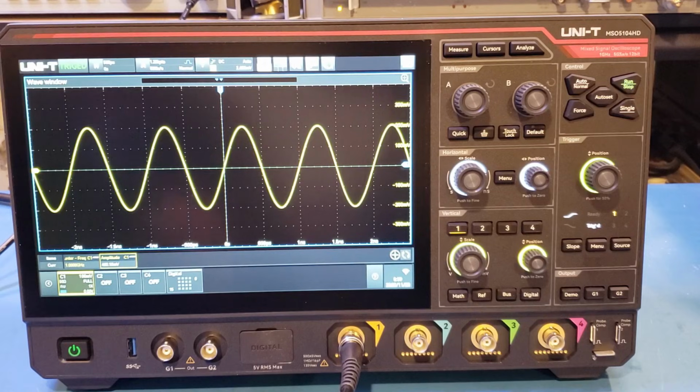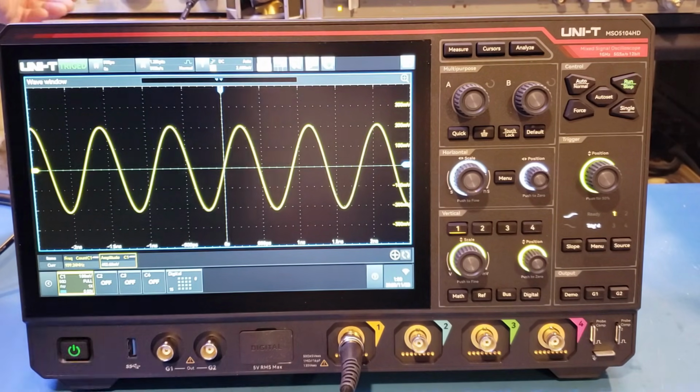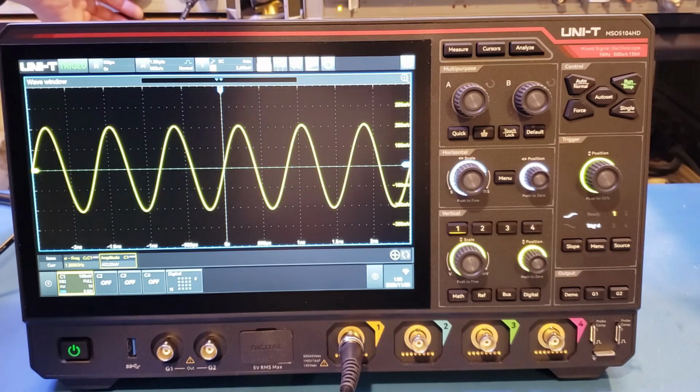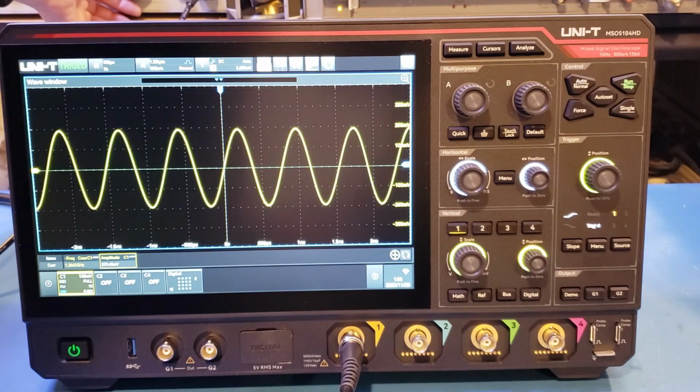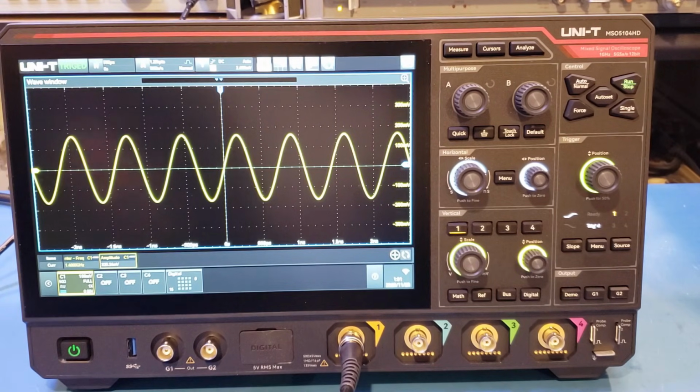And you can see at 1 GHz, we're still at 400 millivolts, so that is still above the 3 dB bandwidth. Now let me increase the frequency a little bit more. Now it's 1.1 GHz, and you can see we're still above 350 millivolts. So let's do 1.2, 1.3, 1.4. So you can see roughly between 1.3 and 1.4 GHz, we actually drop below that 3 dB bandwidth.